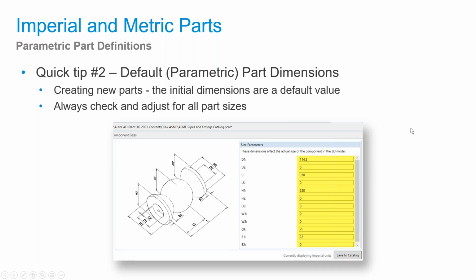If you populate the list of parts over there, each one of those you need to go through and set. The other option, if you have a large number of parts to create, is to use Catalog Builder, where you would export your catalog out to Excel, fill in these values in bulk, and then import them back in and let it build a catalog for you. So this is just a tip if you're editing individual parts in the catalogs.